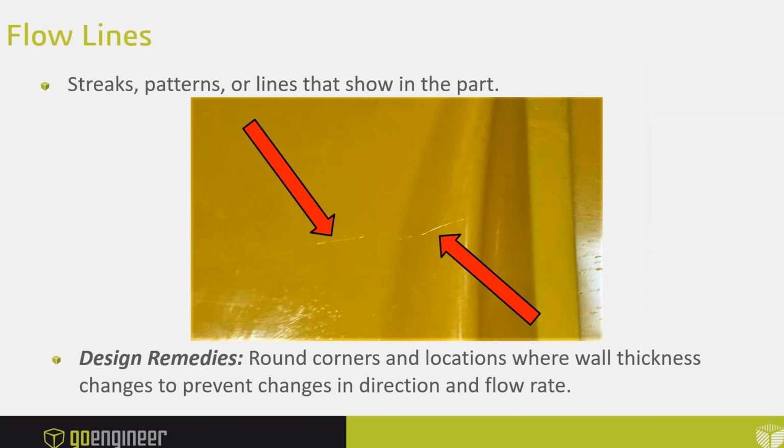Here's an example of a flow line that could have been mitigated with SOLIDWORKS Plastics, right? Again, they look like scratches, but they're not. And if it's on a clear part, they look like a hair inside of the transparent part, but it's not. And the funny thing about transparent parts, we can maybe take it for granted, but transparent parts come out foggy. So when they come out of the machinery, they're not entirely cool. Most plastics come out foggy, and you can't even see through this fog until the part cools after 5 or 10 minutes. So inspecting for weld lines would be an additional process.